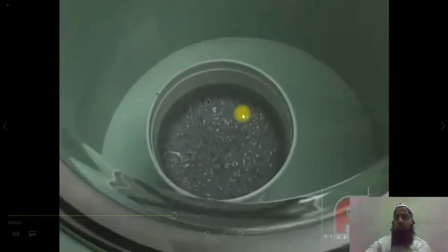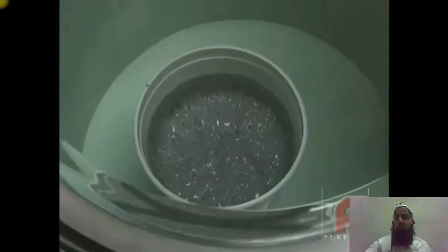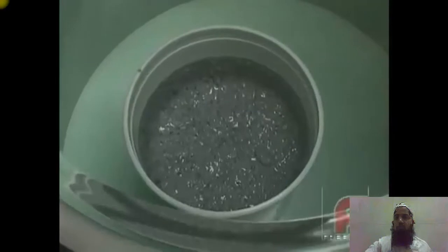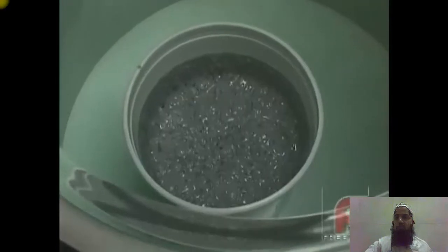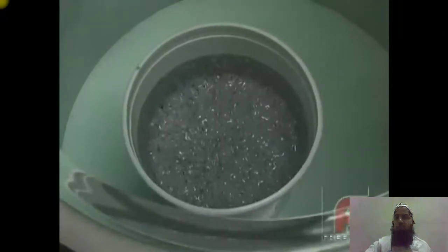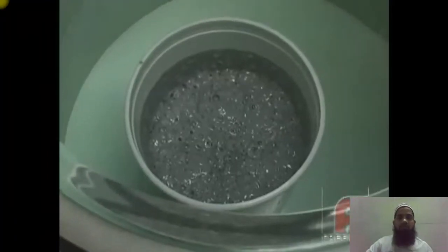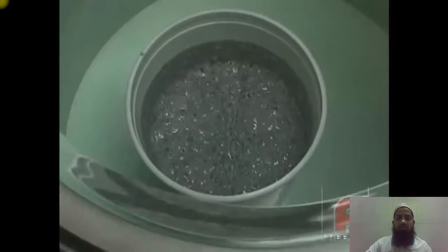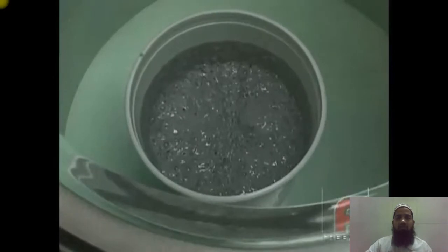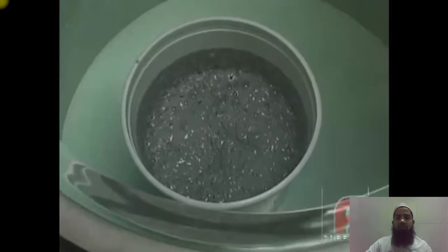While degassing is not necessary for lower viscosity silicones such as V330 and V340, especially for simpler or less demanding casting applications, if you require an optimal, completely void-free mold, we recommend vacuum degassing the material. If you choose not to degas your silicone, you should be careful not to stir the base and catalyst too vigorously, and you should never use a mechanical mixer.